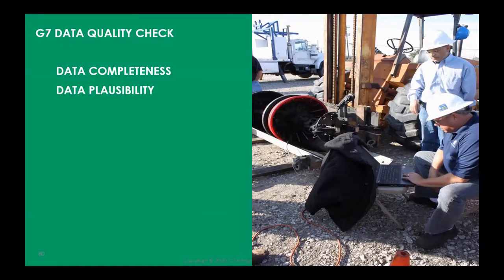How possible is the data that you are seeing, does it correspond to the actual conditions of your pipeline? The amount of data collected not only needs to be complete, but has to be reasonable. The data appears to be what is in your pipeline. Do you see the joints, valves, fittings that you know that you have in your pipeline? Those are important questions to answer.